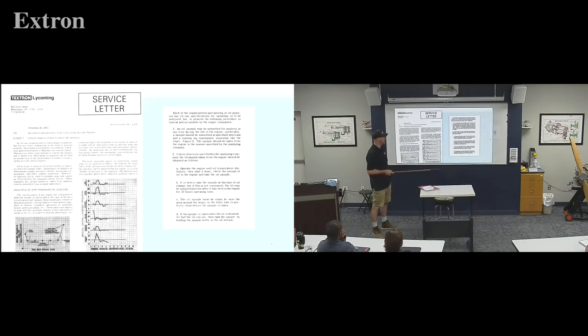Anytime you're wondering if something's going on, but if you want to sample it regularly, operate the engine until the oil temperature stabilizes, shut it down, and basically see how much oil's in your engine. Take the sample at the time of oil change, but if this is not convenient, the oil may be sampled anytime after it has been in the engine for 10 hours operating time. So they're saying don't take an oil sample after you only put it in for 1 hour.